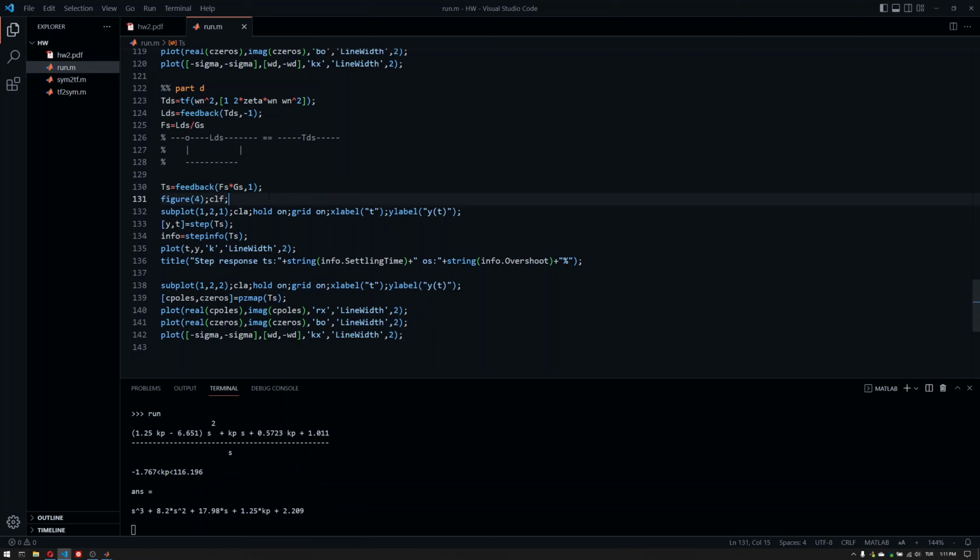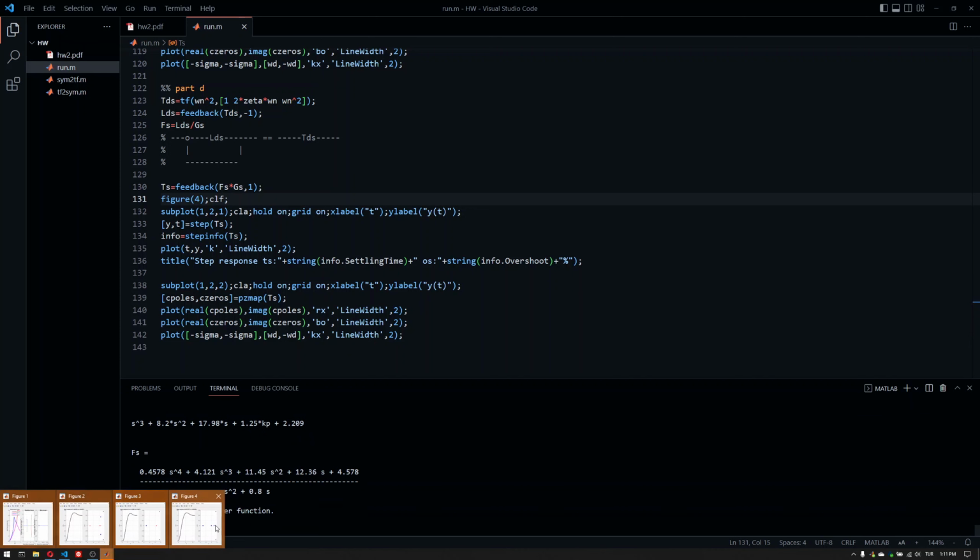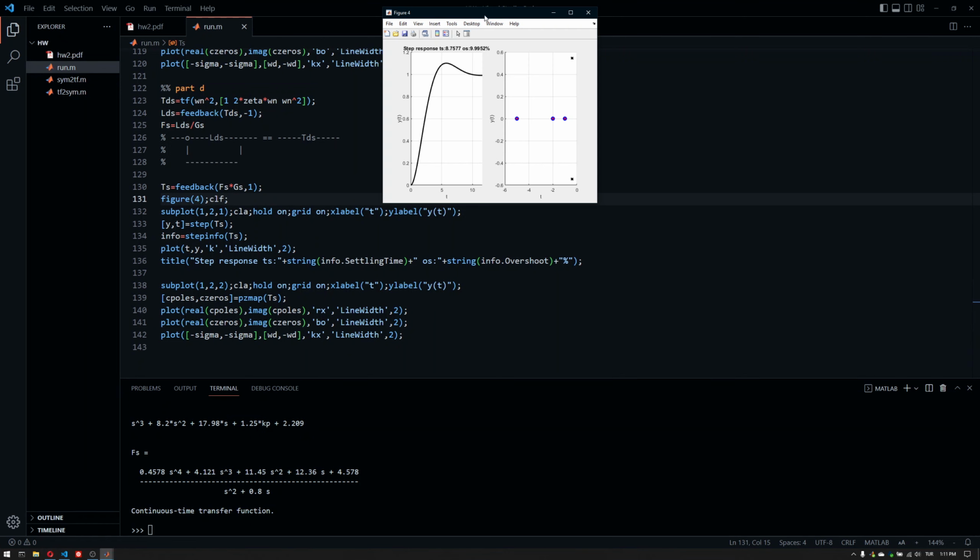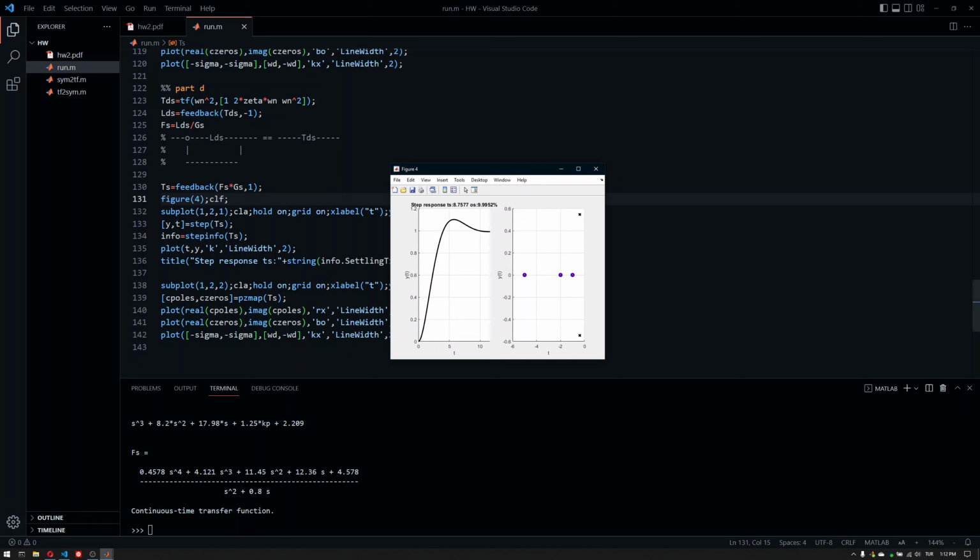And in terms of dominance factor, since we've got rid of all the residue poles and zeros, there are no zeros, no residue poles, it's going to be infinity because we have a pole at infinity, we can assume that. Therefore, we will have basically infinity for the dominance factor here. So as you can see, this is the ideal setup here. We've cancelled out everything here. We have just these two poles, and that's basically it.